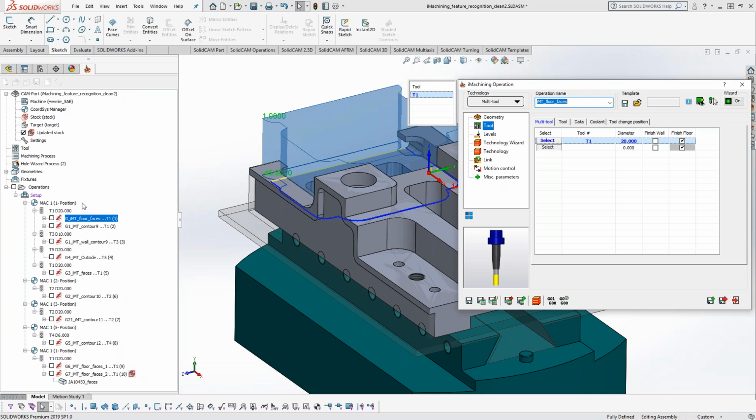So if you wanted to pre-drill several pockets with different levels with one drilling, which I recommend, because if you do have closed pockets, the best thing you can do is to pre-drill the holes. Even if you're just drilling out the center of the hole, it really does help the end mill with helical entry.